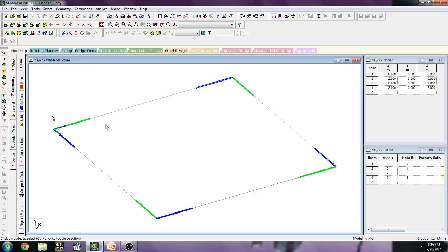And another one is the local axis. If you want to show what exactly the local axis is, you should press Shift plus O. If I press Shift plus O, four different axes appear on the different members' sides. Each axis represents that member's local axis system, because as I already said, every member has its own local axis. These local axes change with the place and position of the member.